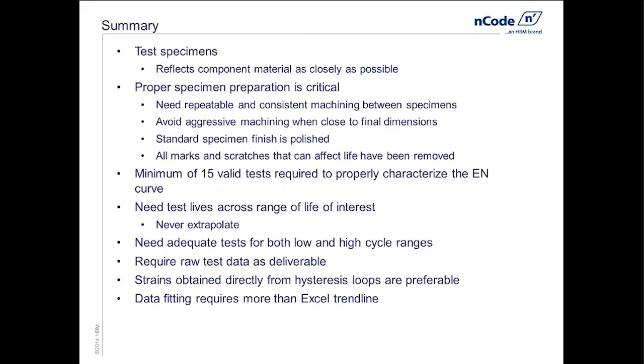Again, the test specimens. We want the specimens to be made of material that as closely as possible represents the material of our part: composition, microstructure, heat treat. The preparation of the specimens is critical. We want to guarantee that the specimen is dimensionally correct, with minimal variation across specimens, as well as a geometry such that as I apply a tension load, I'm not inducing things like bending because of misalignment of the specimen.